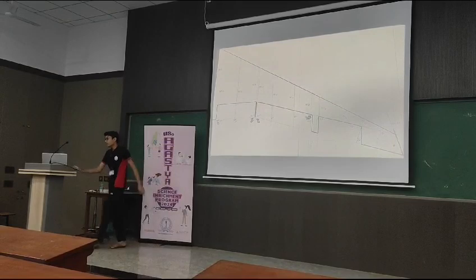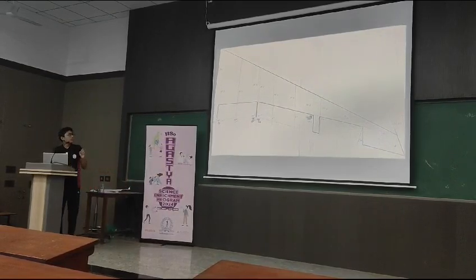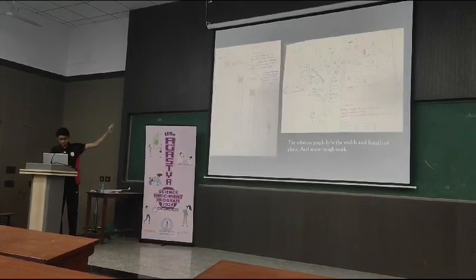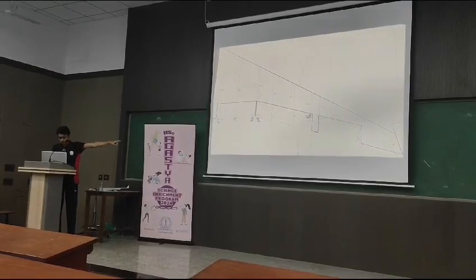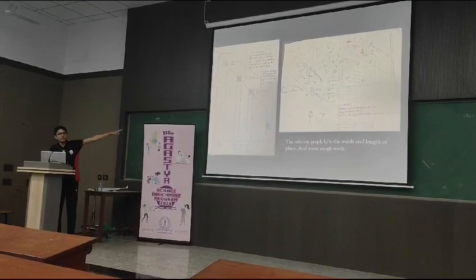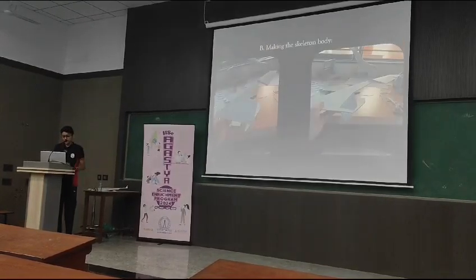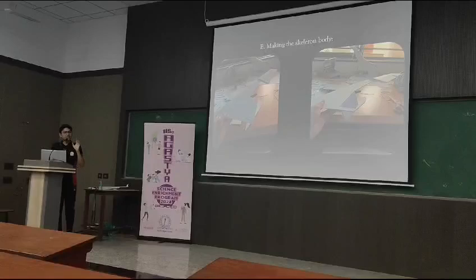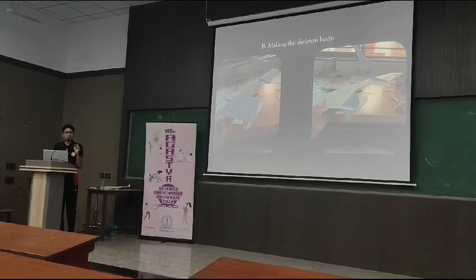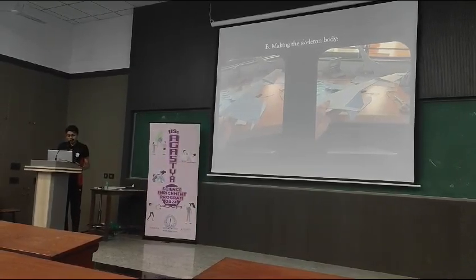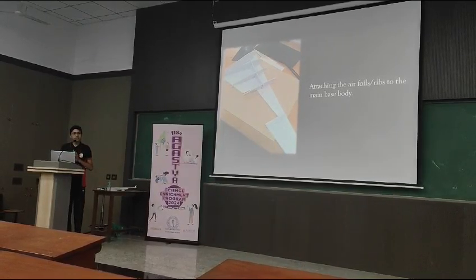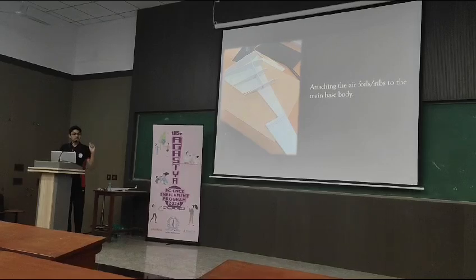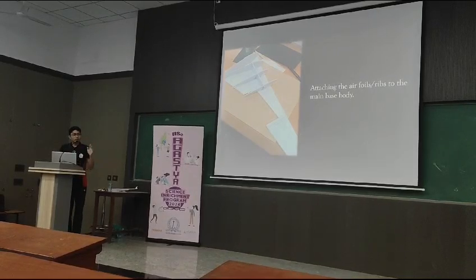At this point, the maximum width of the airfoil is 1.5 inches. And the last one is at 16 inches, where the width is 0.5 inches. That's the relation graph. After that, first I made the skeleton body, the base with a 3 mm foam sheet. After that, I stuck the airfoils as needed, as in the sketch diagram. I added 12 airfoils.